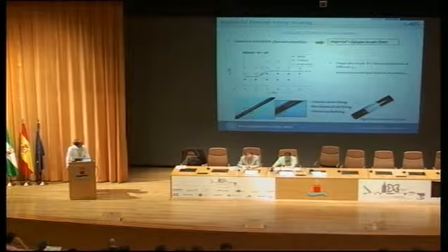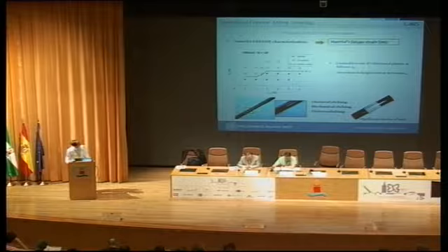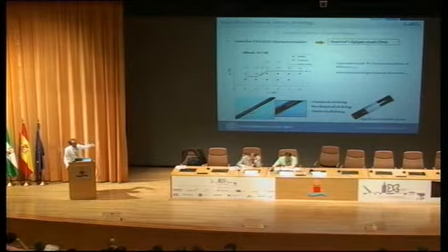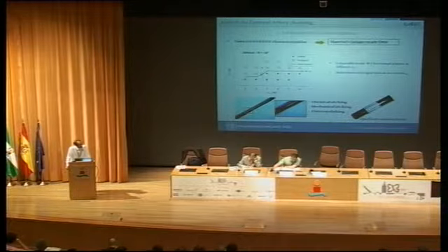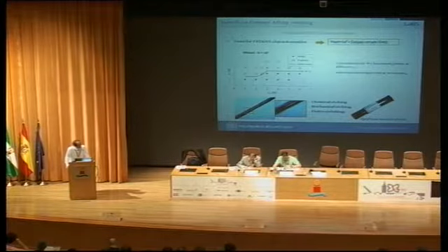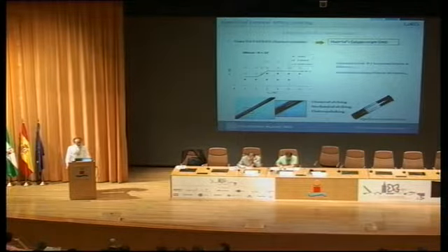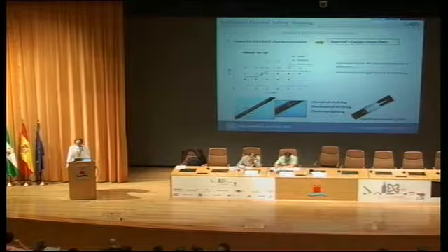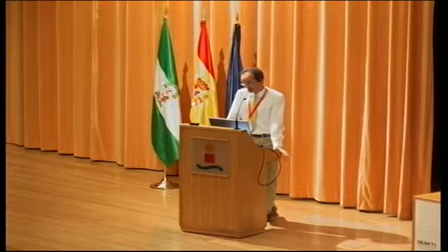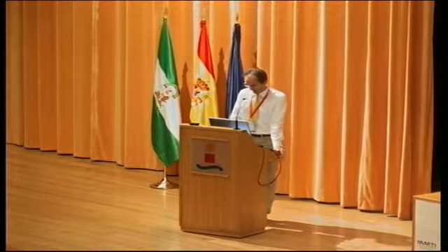And in this case, as you can see here, each square is an experimental point, an experimental wire, and the dark ones are those which were not fractured, while the white boxes are the fractures. We can identify a limit curve, the red one, which separates the probability of fracture from those that don't fracture. And the peculiarity of this curve is that we have two horizontal plateaux, and that we have an improvement in fatigue limit for the nitinol when we increase the strain.